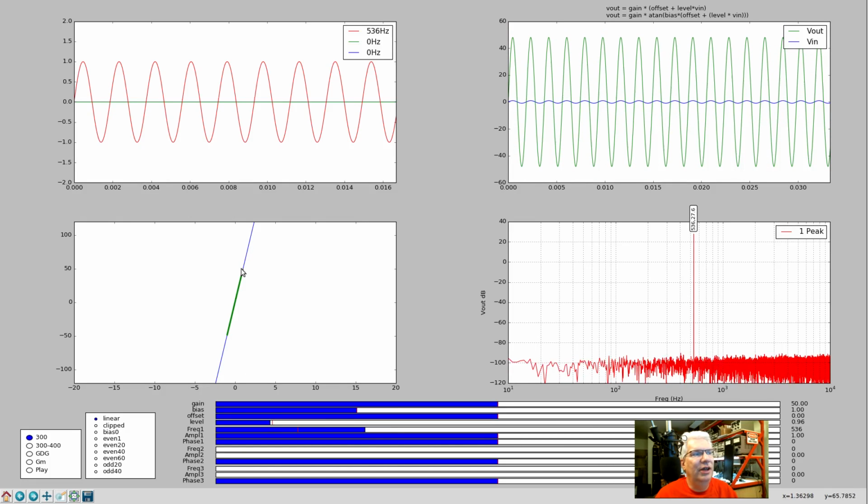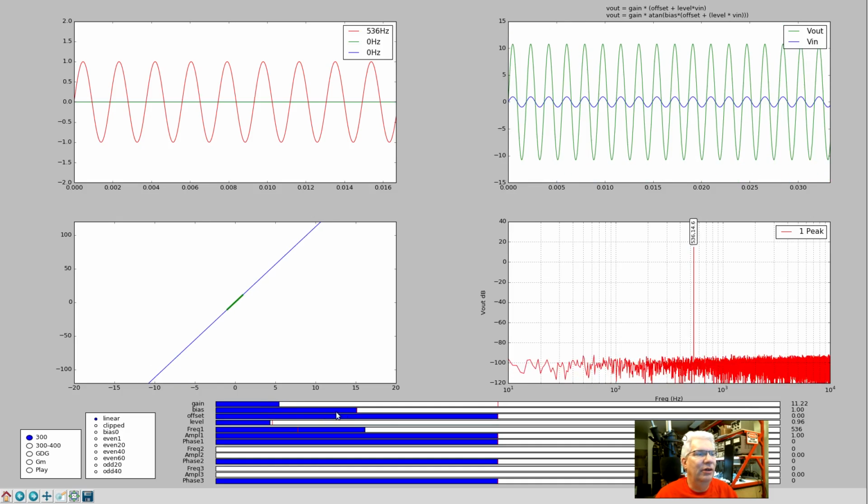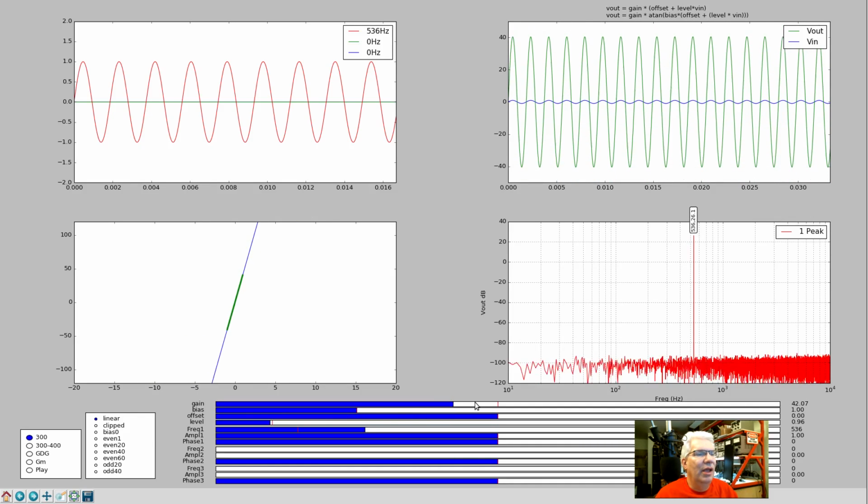And you can also see down here, this is our gain stage. We can change the characteristic of that gain stage by changing the gain slider here, which effectively changes the slope of this linear amplifier. We'll talk a little bit about the bias in a minute. There are some equations up here that tell you what's going on if you're running clean, or linear or not linear.